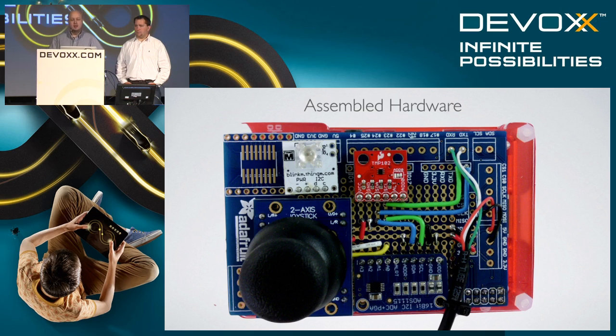So I took a board that sits on top of the Pi. It just plugs in nicely on top, which is a prototype board that you can then solder wires onto for all your other boards. I took these 4 little boards, which took me a couple of hours, and put some wires up. Basically, I just have the I2C buses connected up to each of the little boards, and then there's a couple of wires connecting up the analog pins from the two-axis joystick up to the inputs of A0 and A1 at the bottom there for the analog to digital. So it's pretty simple to put together your own board.